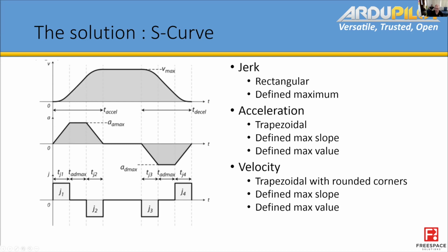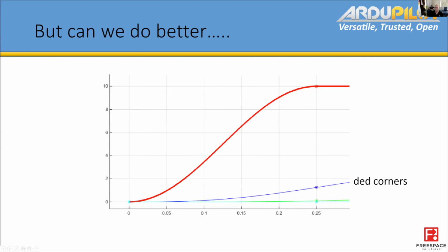So in order to actually make an aircraft confidence inspiring, we need to not only limit the rate of change of acceleration, which is really nice, because otherwise it would just belt it at whatever angle it needed to do that acceleration. We also would like smooth transients in our jerk response. So this is what we've come up with. Now, this red line here is the new jerk response. Now, this is a raised cosine function.